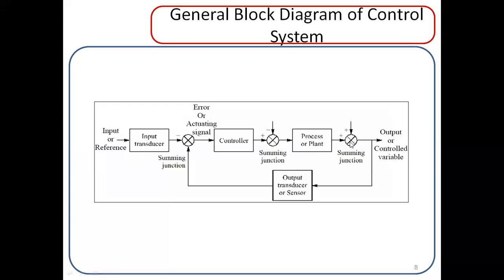These results will be verified here, and those results will be fed back by a transducer or a sensor to the reference channel. And here the comparison will take place between the reference and the obtained results as feedback. If there are any further modifications, those errors will be identified. For example, you need to get the breadth as 2.6, and length and depth have been satisfied as per the input or reference values, and we have to monitor only that particular breadth. Depending upon the breadth, how much it has to be progressed? We have got an error of 0.02 mm, and that needs to be compensated, and only that particular set of instructions will be highlighted with the help of this controller.